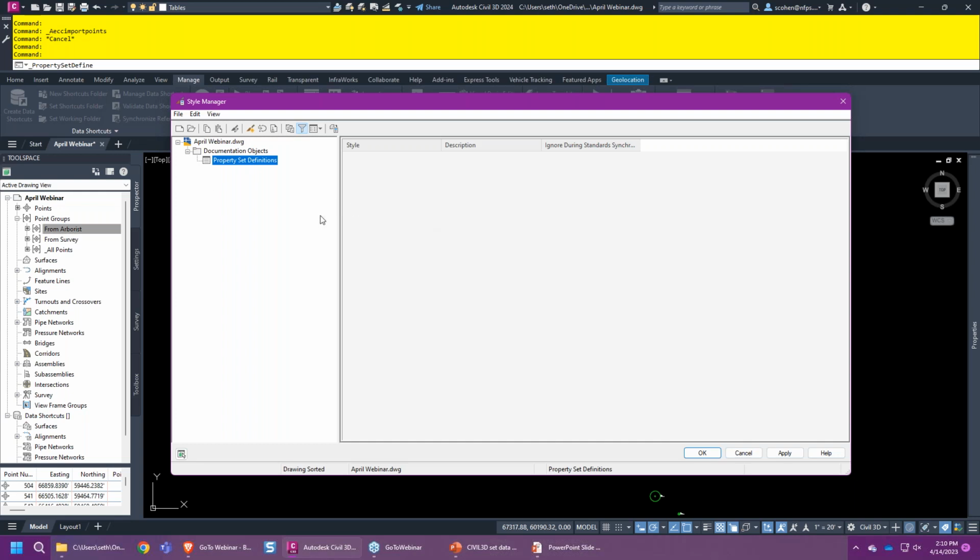Now, one thing before I even get into this, I want to show right off the bat, because I was working with certain types of this functionality, and I couldn't find the categories, because I don't use AutoCAD Architecture. Again, that's where this comes from. The second you run that command, right over here, you don't notice it, but if you look closely, it's grayed out or grayish, like it's highlighted. I'm colorblind, so it looks kind of bluish to me. Someone will say, hey, Seth, that's not the color, but it looks cyanish to me. But this is actually a filter, and it does activate the second you run that command. So if you turn this off, notice what happens. You have access to the rest of the style manager functionality.